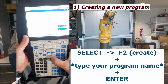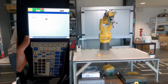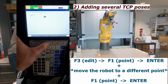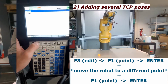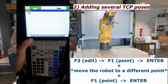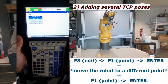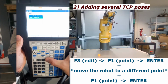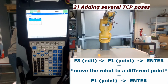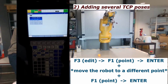After typing the program name, we press enter and here we are. Now, for editing our recently created program, we should press the F3 key. For the option edit, we can record the position and orientation of the tool center point, also known as TCP. For saving the TCP first position, we should press the F1 key for the point option and then press enter.